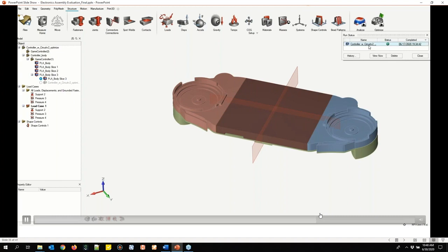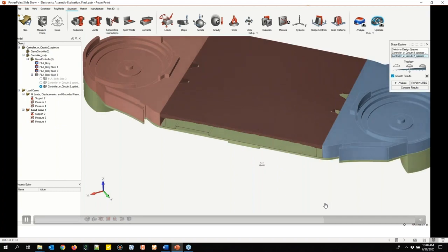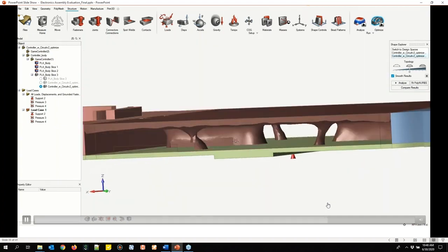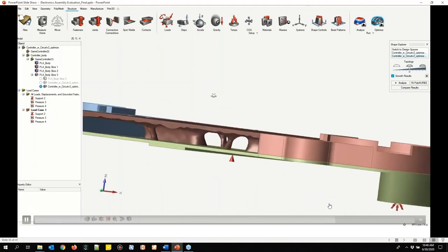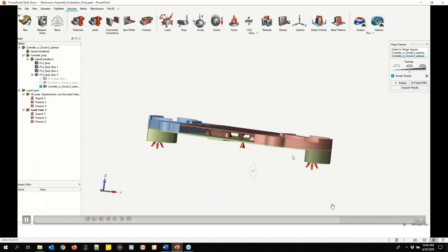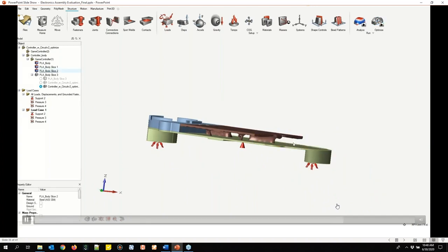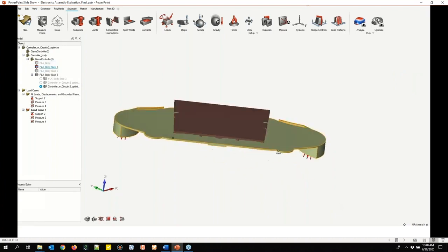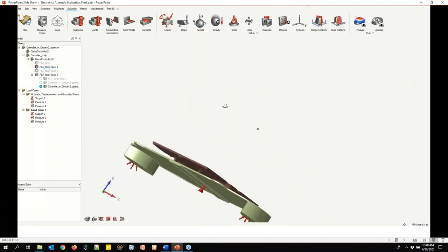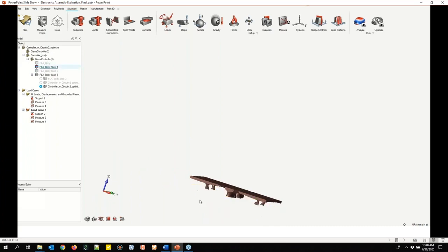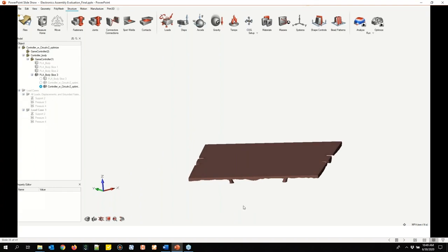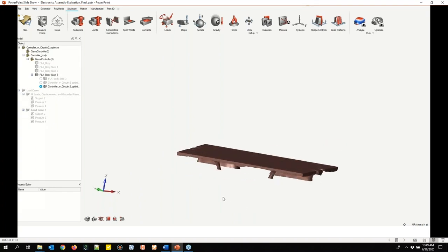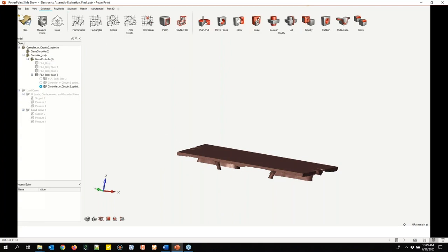So once this is finished running, if we look at these results, we can see that if we zoom in here, the concept creates these cavities and creates a top face of our controller, which is feasible manufacturing-wise because we do want a top face on our controller. And if we isolate out this design, we can see that the shape follows an I-beam, right? So I think this is an interesting concept because it's a classic case of the optimizing tool giving us a design generation concept that's grounded in real-life physics and reality.